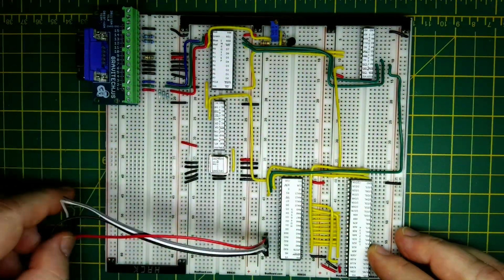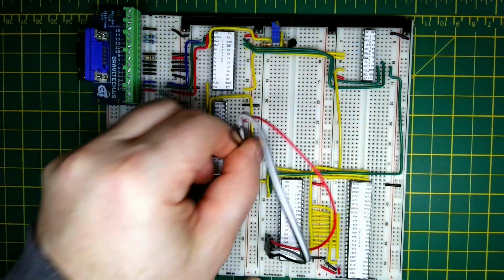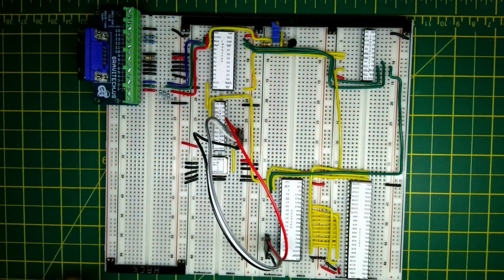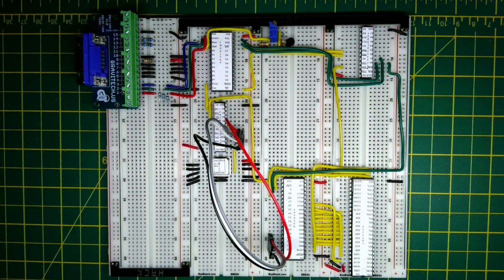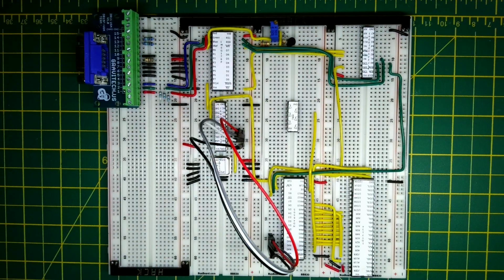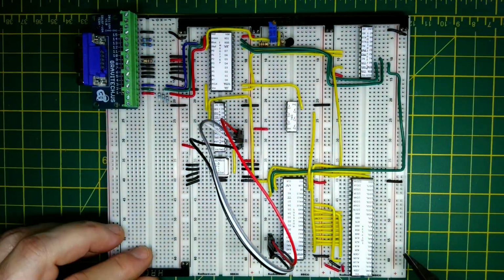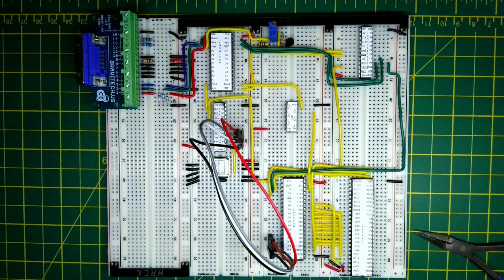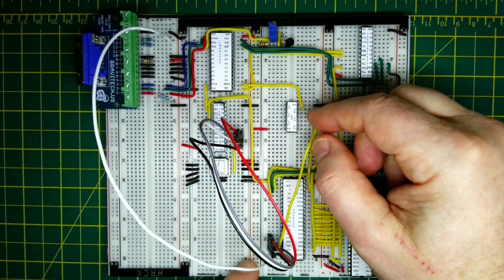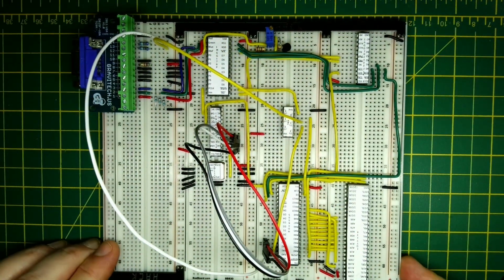So now we're going to wire up the raster row address lines up to the PLD there. Just a temporary measure for the moment. Now we do need to temporarily put an inverter in for the display enable to go into the blank input to the video DAC. This will come from a PLD on the left hand side a bit later. Then we're wiring in vertical sync and horizontal sync. Horizontal sync also needs to be inverted as well.